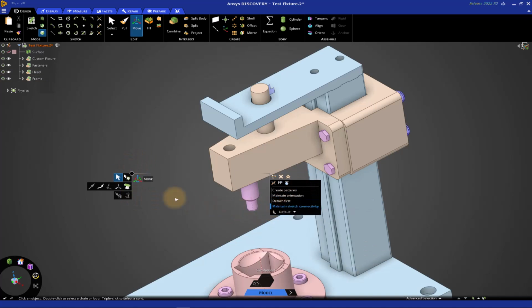Once the Move tool is on, we'll see the heads-up display or the HUD in front of us here, and on the left-hand side we have the tool guides, and on the right-hand side we have the options, just like in Pull. They're organized and pretty similar between Move and Pull. The first row is selection, and you can select geometry like faces and edges, or you can also select components. By default, we're moving it in a direction, and you can change that direction, but you could also move along a trajectory. You may want to reposition where the anchor is, or move radially, or about a fulcrum.